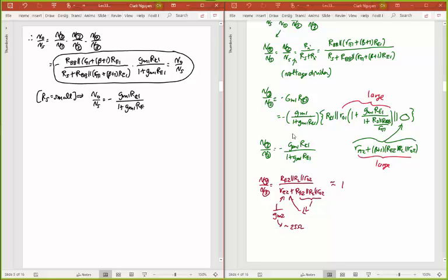Just ignore that first voltage divider term, which basically goes to 1 if RS is very small. Okay? So if you're going to be very accurate about everything, your equations can be a bit intimidating, but often it's not needed to be this accurate. So this whole thing boils down to something that you could have done in less than 30 seconds if you just had the experience to know that that first stage gain is about 1, that last stage gain is about 1. All you had to do was look at the second stage and just write down this.